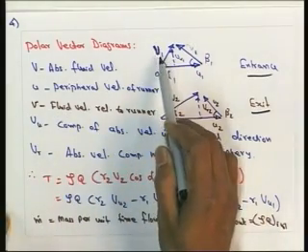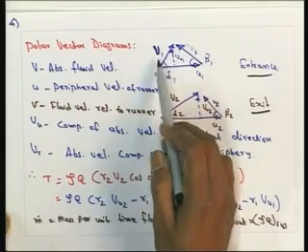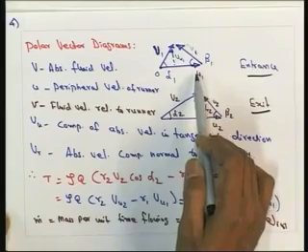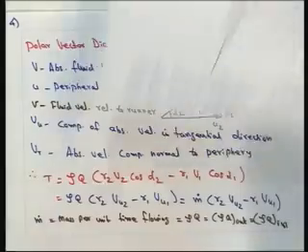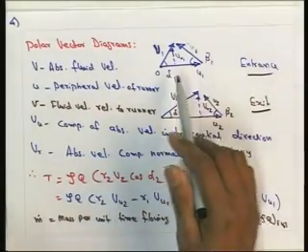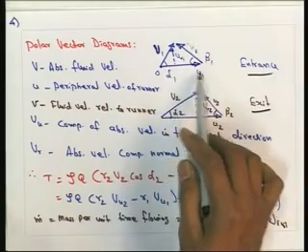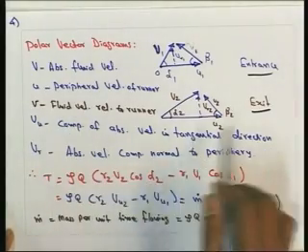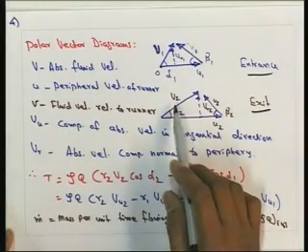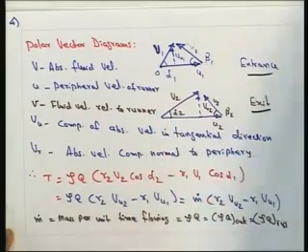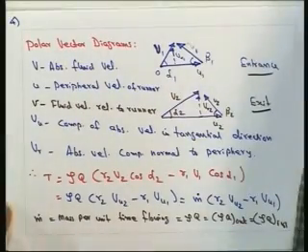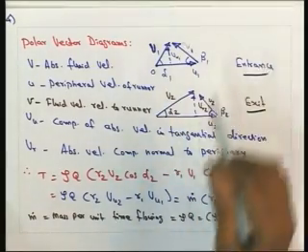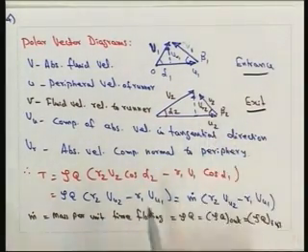So, V1 is the absolute fluid velocity for the entrance, and U1 is the peripheral velocity of the runner, and VR1 is the radial velocity. For the exit conditions, V2 is the absolute fluid velocity, U2 is the peripheral velocity of the runner, and beta 2 is the corresponding angle.